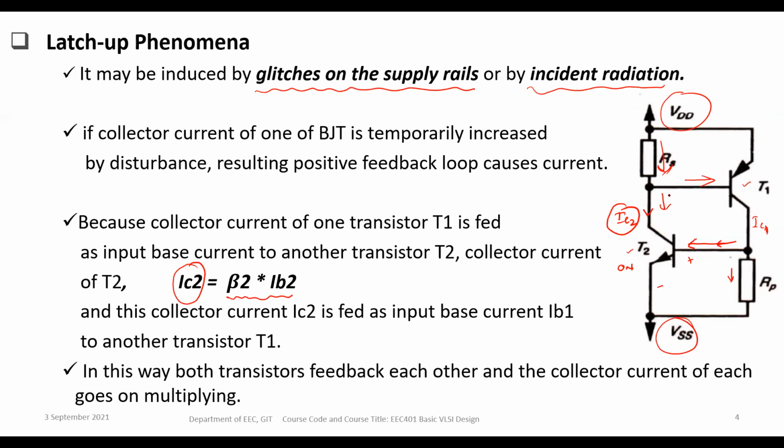What is the amount of the current flowing here actually? So that means this IC2 will influence IC1, because the current flowing here will be the base current. That base current, as we know, the drop across it will also activate this device. So this device becomes on, and some amount of current will flow. Therefore this process will be repeated. This feedback current flow is repeated.